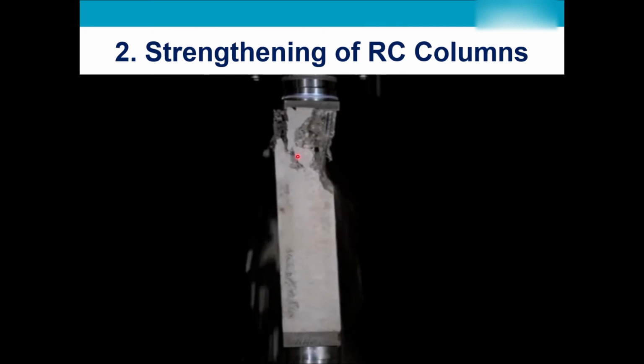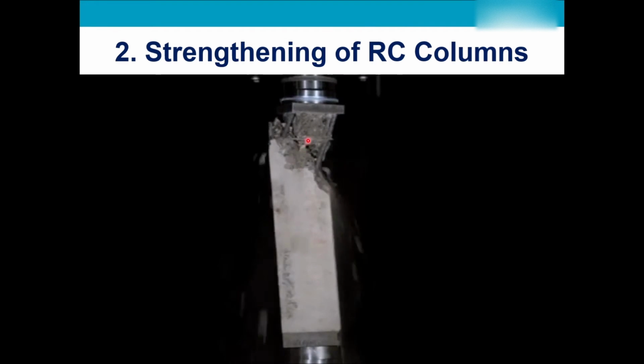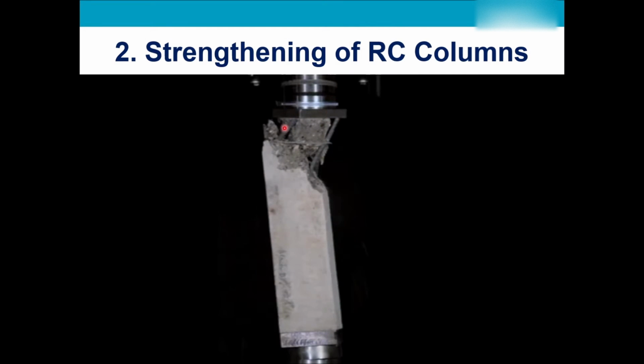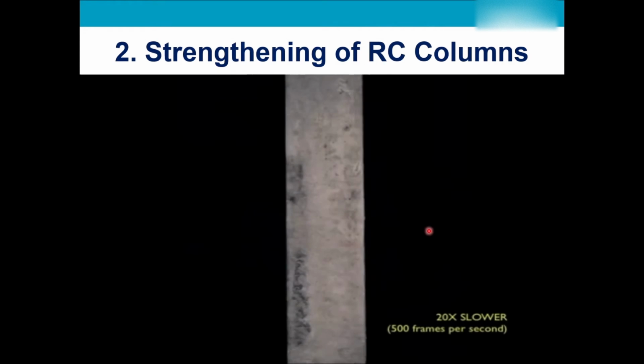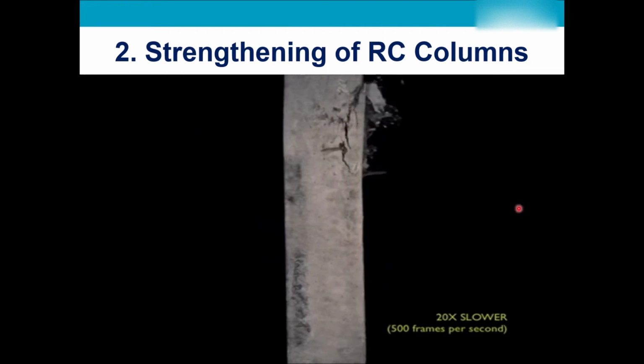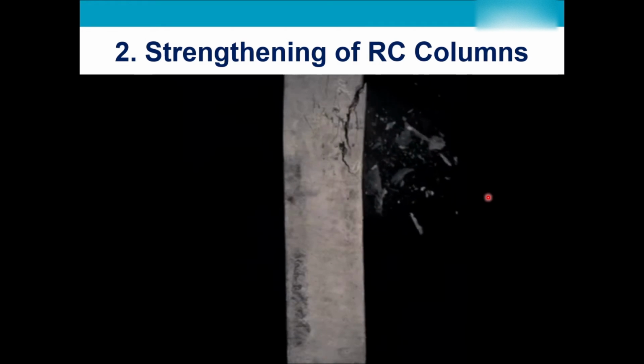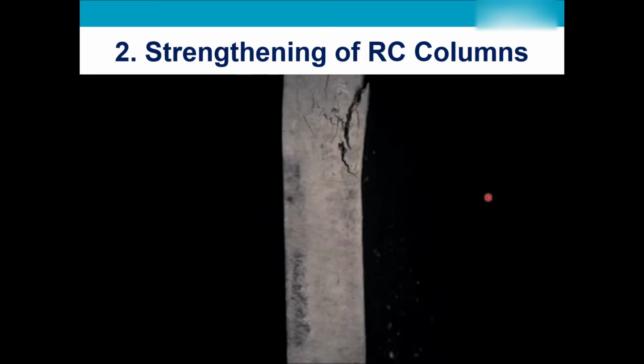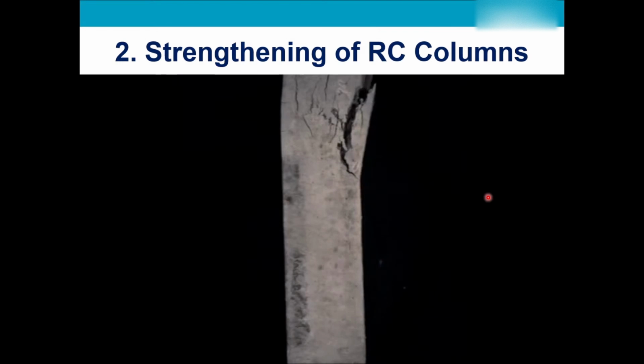You can see the bending, you can see the deformation, the proper buckling of your column. You can see how much non-linear behavior the steel has, the shear reinforcement has, the core of the concrete and the covers. Let's slow it down and see what happens. So definitely a failure of the cover. This is an unconfined concrete. We carry on with the loading, more axial load.